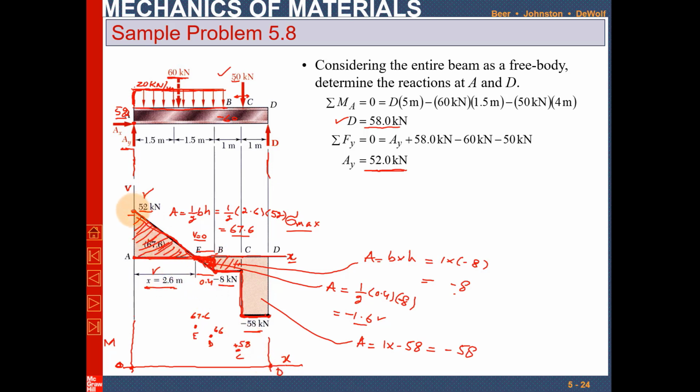You can see that the shear force diagram between point A and E is a linear line, but the slope is decreasing. So the bending moment diagram will be a second degree equation, and it will be a curve. Now from point E to B, it is again a first degree line and the slope is decreasing, so it will again be a curve.